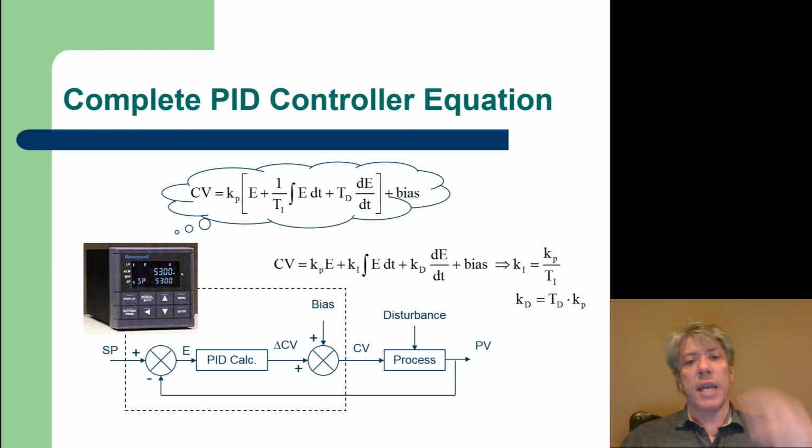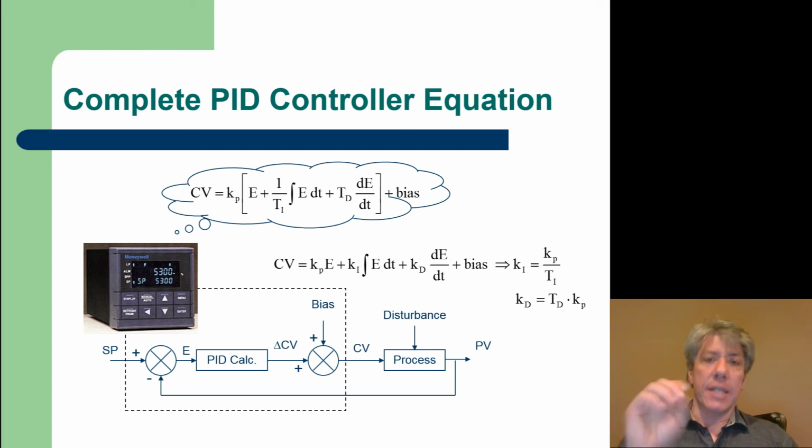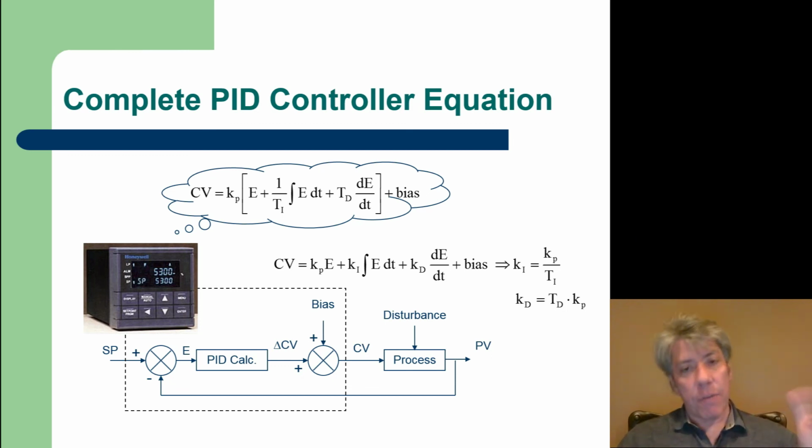But then there's a TI parameter, 1 over TI, which helps you adjust how sensitive the controller is to the integral term, or the accumulation term, and another gain, T sub D, that is multiplied by the derivative term in order to affect it. Now notice Kp, when you change it, affects the effective magnitude of all of these terms. It changes them all. The reason is that often it's easier to tune the controller if the proportional gain changes all of these together.